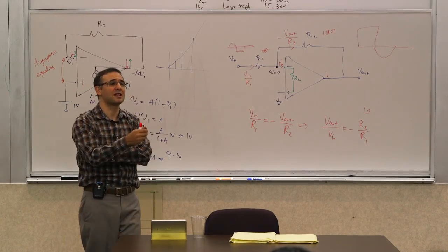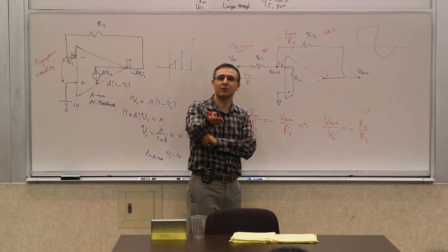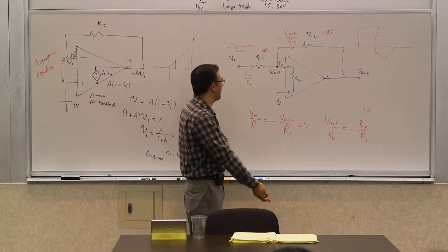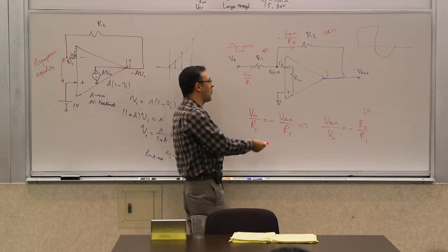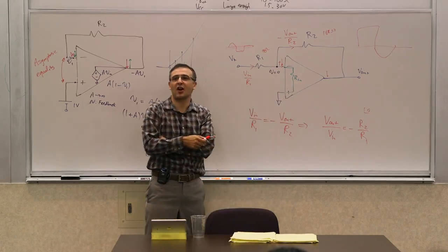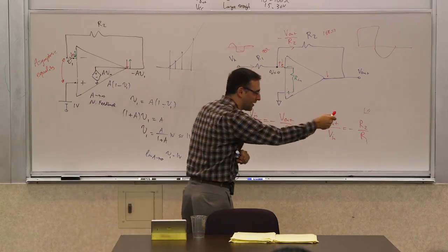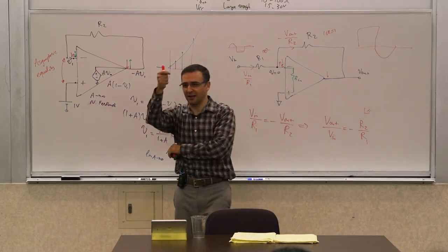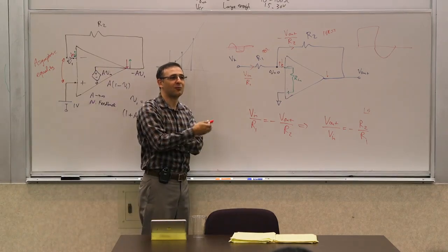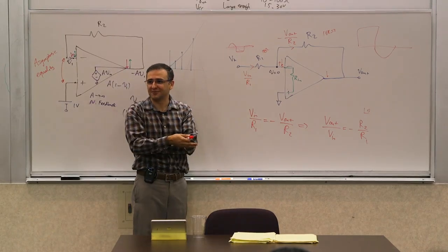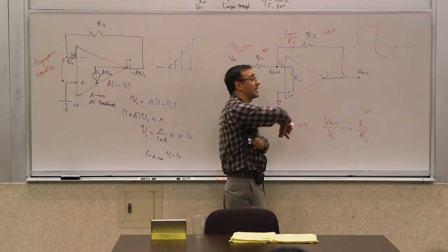Okay, so that's a good point. She said if you started with something that had a specific gain to begin with, you can only use it for that. This one has versatility, flexibility, because you can actually change these resistors and get different gains. That is true. That's a correct statement. So with one kind of thing, instead of stocking the stock room with 10,000 different kinds of amplifiers, a gain of 2 amplifier, gain of 3, gain of 4, gain of 5, gain of 6, gain of 10, gain of 12, you can just have one that you can get everything out of, and you stock it with a few resistors, which are a lot cheaper. So you can control the resistor, you can change it.